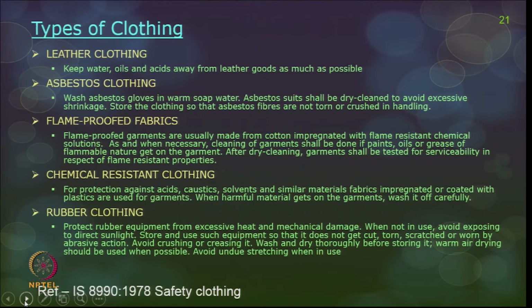Flame proofed fabrics. Flame proofed garments are usually made from cotton impregnated with flame resistant chemical solutions, and often the garments may be stained with paints or oil or grease. It should be properly cleaned off the garment by dry cleaning. After dry cleaning, the garments should be tested for their strength and resistivity, and only then should they be used for the next round of work.